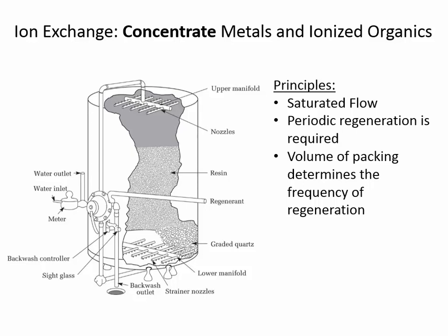No, you wouldn't put it back through again. Let me draw on the board here. So what we would say is maybe for 24 hours, we have water going this way, and so the dirty water goes in, and the clean water comes out for 24 hours. But then this becomes full. Whatever it is we're trying to remove, let's say if it was chromium, this becomes full with the chromium, and so now we have to get it out, because once it's full, then it can't clean the water anymore.